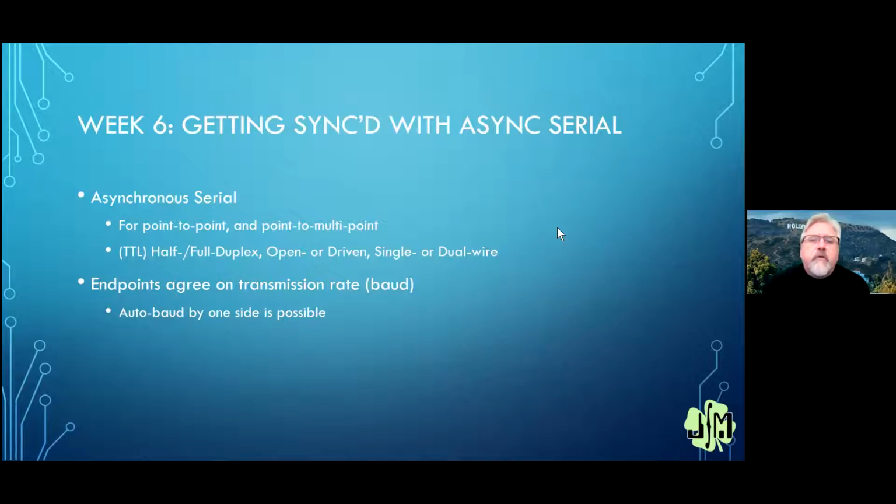We can also do multi-point stuff. That's something I get involved in a lot with DMX and other RS-485 things. So I'm going to talk about that a little bit. And certainly when we get to the XB stuff in a couple of weeks, that can be point-to-point or point-to-multi-point. And here we're talking about the data mostly. Now, the things we're going to do frequently will be over a wired system, but as I just pointed out, XB is wireless serial. And now there are some complicated and sophisticated protocols running underneath. The nice thing is they are running underneath and they're kind of abstracted for us.